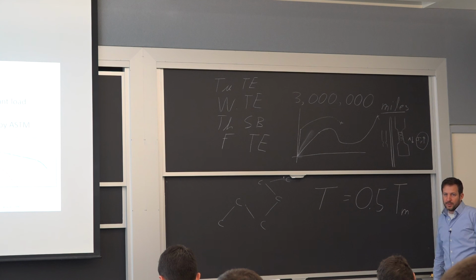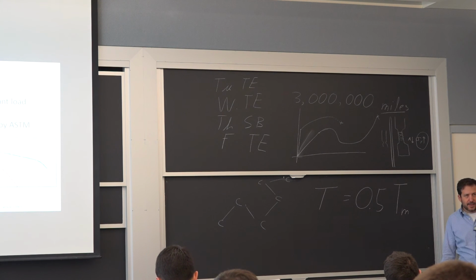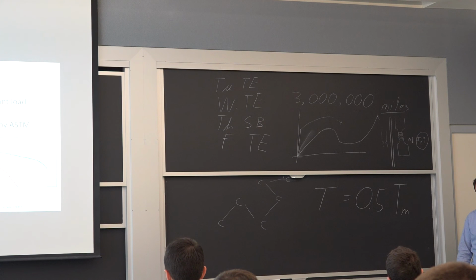This is in Kelvin. So if we're thinking about steel, and I skipped that part because I just wanted to give something interesting that was different today. If we're thinking about steel, steel melts at 1600 degrees centigrade, so 1900 Kelvin, 1000 Kelvin, which is about 700 centigrade, it's going to start to creep just like the plastic, but most of the time we don't care.